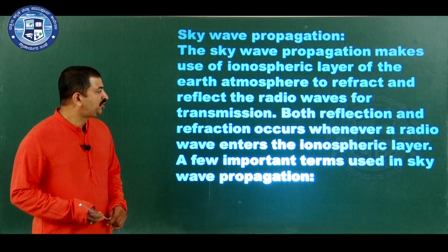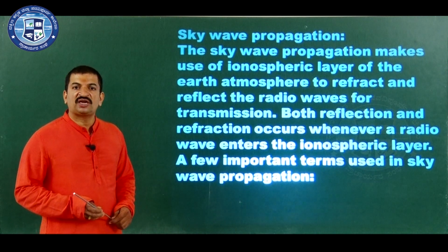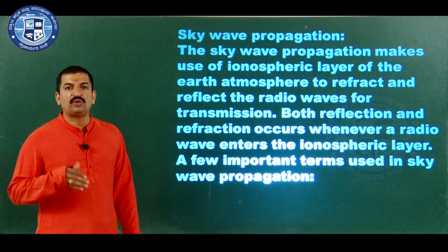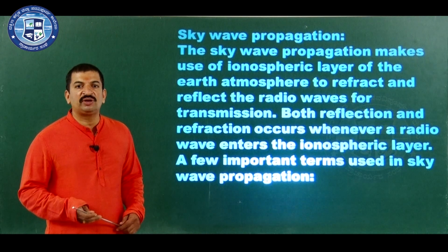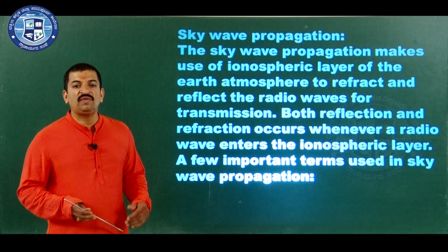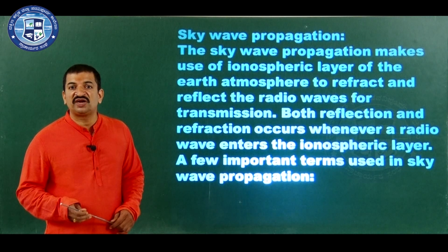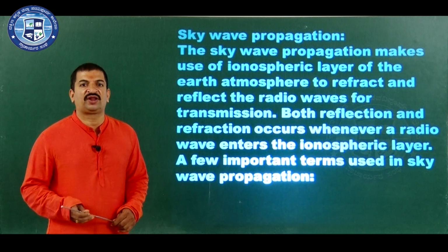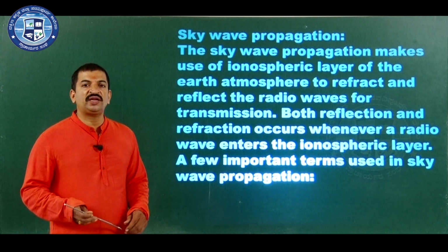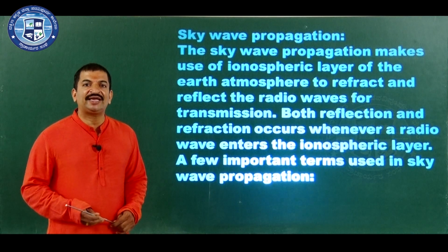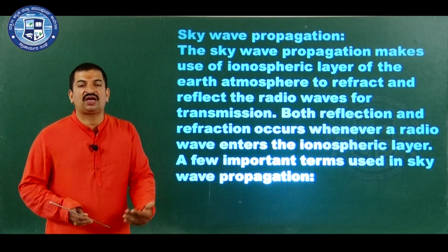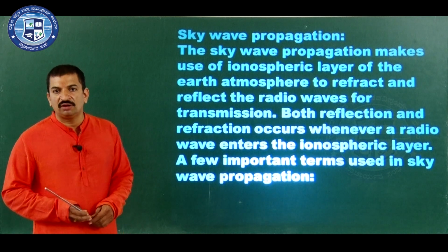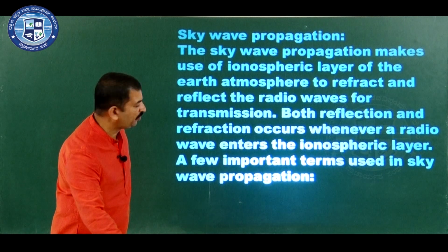Now, low frequency signals can be transmitted very easily compared to high frequency signals. As the frequency of the radio wave is gradually increased, the ray will find it very difficult to get reflected back to the earth. This is at a particular frequency called the critical frequency. If the transmitting frequency is increased beyond this critical frequency, the ray will not be returned down to earth; it escapes from the earth atmosphere. Now, what is critical frequency?